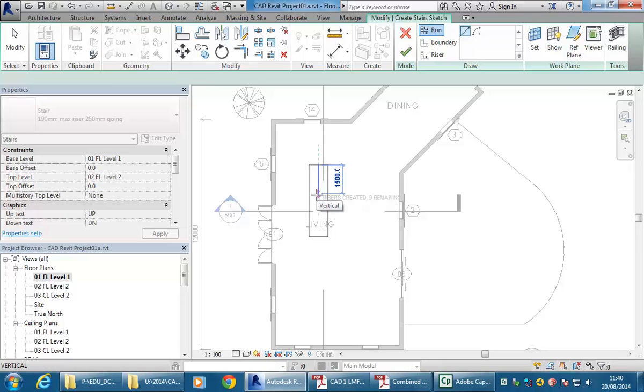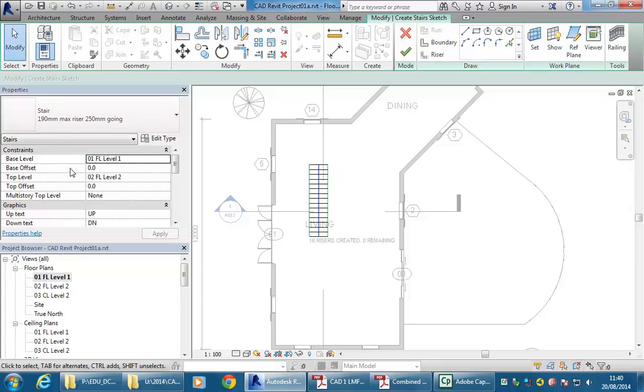Yeah, exactly. And so the trick there, if you want it to be a straight stair, is just take it all the way to the end of that rectangle, or past the end of that rectangle that it makes. And that will create all the rises you need to get to the next level. This is 18. Or 16, sorry. The program automatically calculated for you, to keep a distance between the steps. That's right, it works it out.